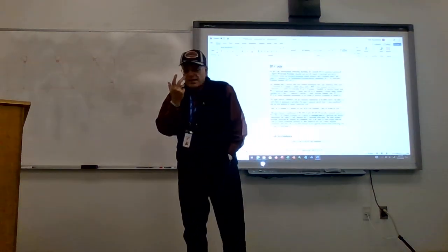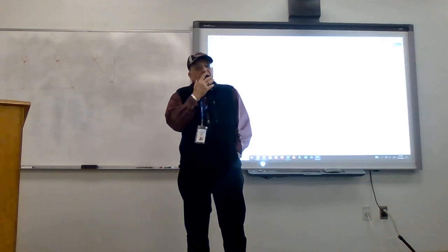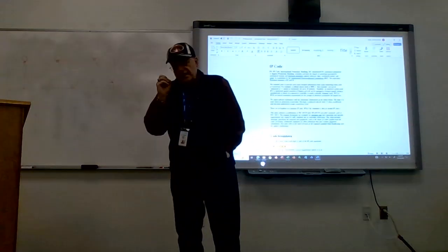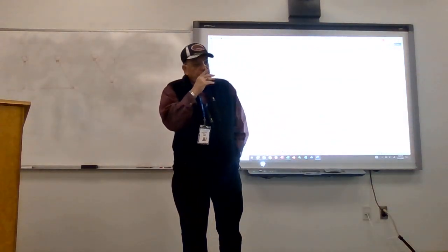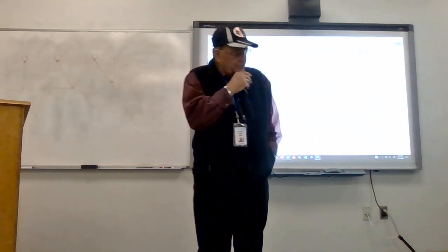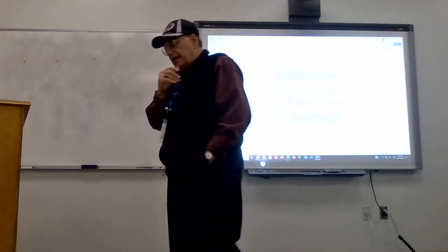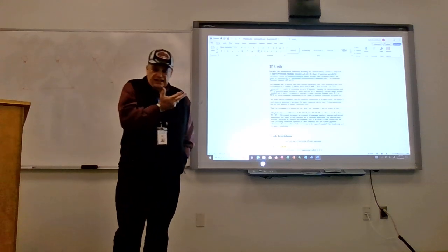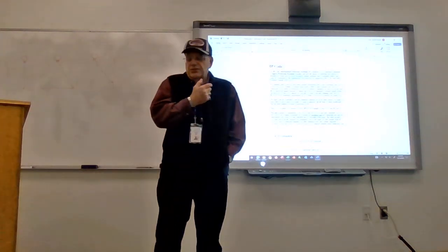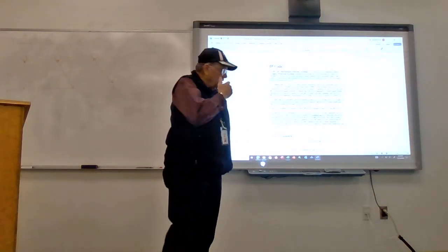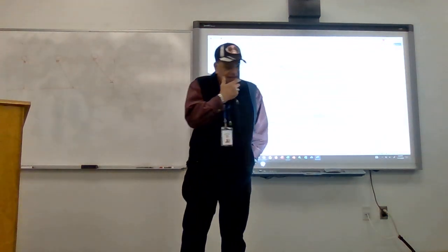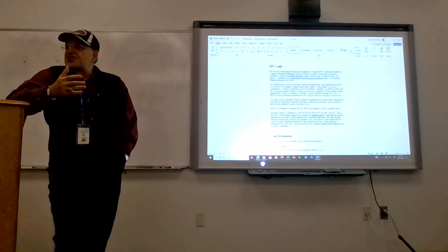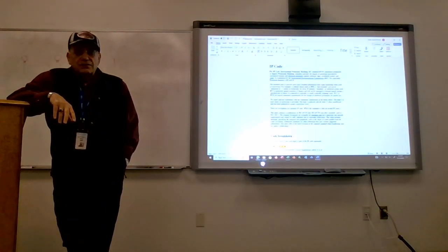Okay, so today's lecture is about the math behind the lighting results. Basically, we're going to do calculations to show you how we derive foot candles, or how we determine the number of luminaires necessary to properly light a space. I like to talk about this as a science lab course, okay?